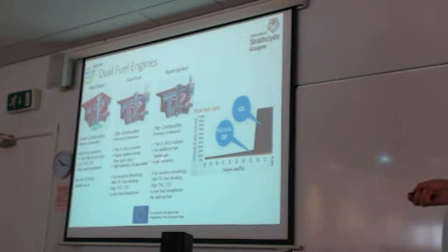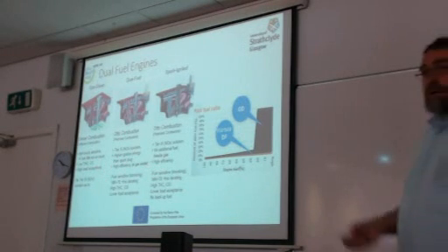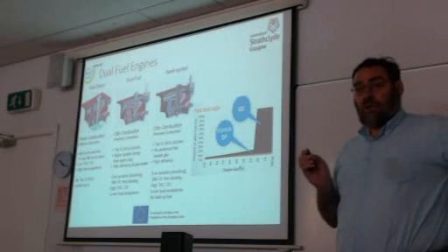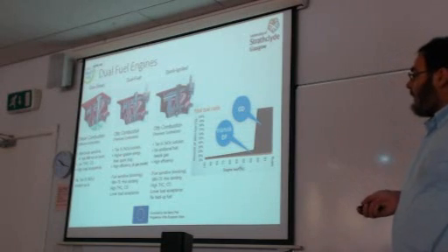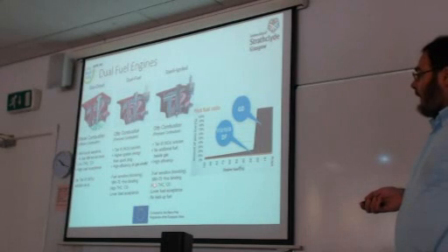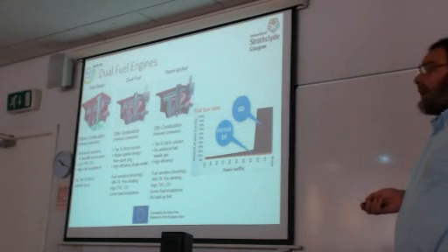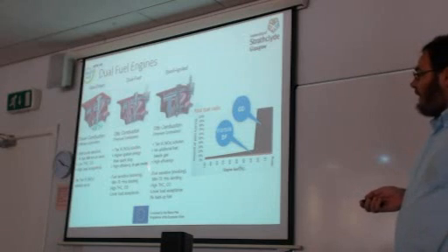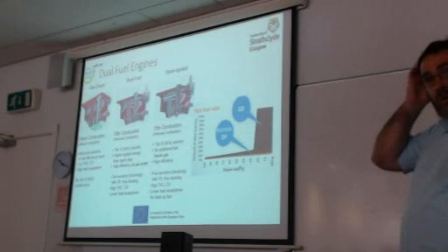There is no additional fuel, but this can be a disadvantage when we take into account the redundancy required onboard the ship. High efficiency can be obtained, and this high efficiency can be explained by the different carbon-hydrogen ratio of natural gas. Of course, again, as it's premixed combustion, the engine is fuel sensitive at NOx, so a lambda operating window is required.